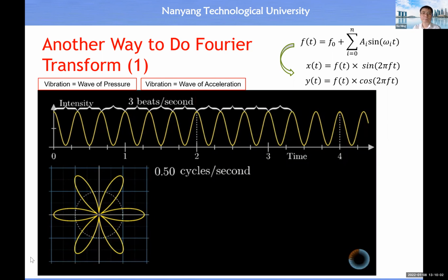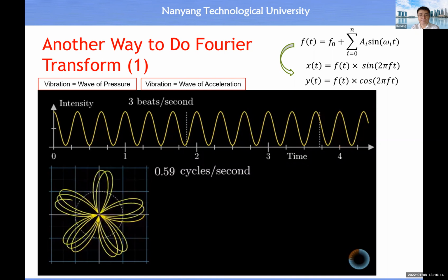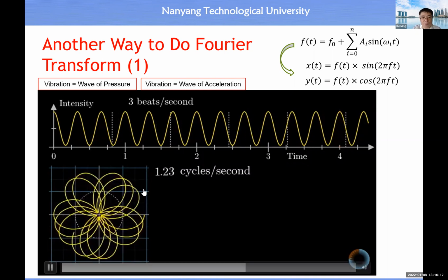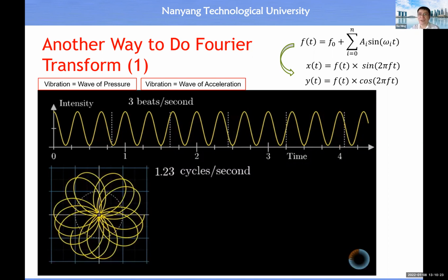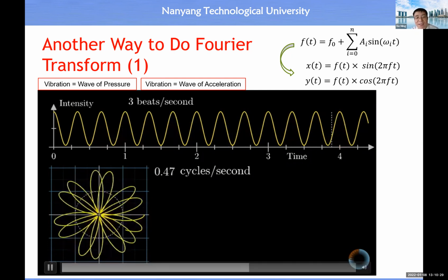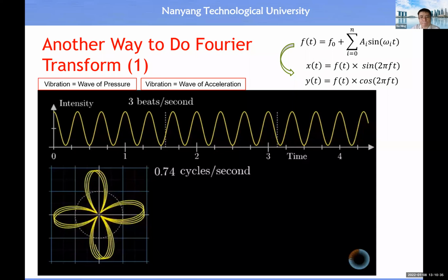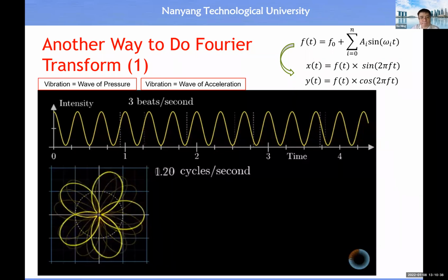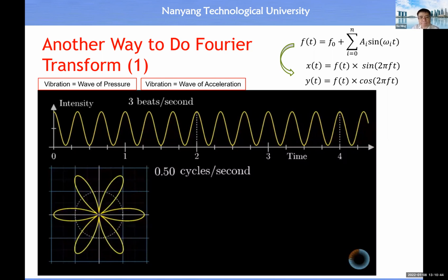And then separately, there's the frequency with which we're wrapping the graph around the circle, which at the moment is half of a rotation per second. But we can adjust that second frequency however we want. Maybe we want to wrap it around faster. So you see, we vary this one. That means scanning through all the possible values, okay, from 0 to infinity, for example, all right? Or maybe we go and wrap it around slower. Then you see when you reach 3, and that choice of winding frequency determines what the wound up graph looks like. Some of the diagrams that come out of this can be pretty complicated, although they are very pretty. But it's important to keep in mind that all that's happening here is that we're wrapping the signal around a circle.